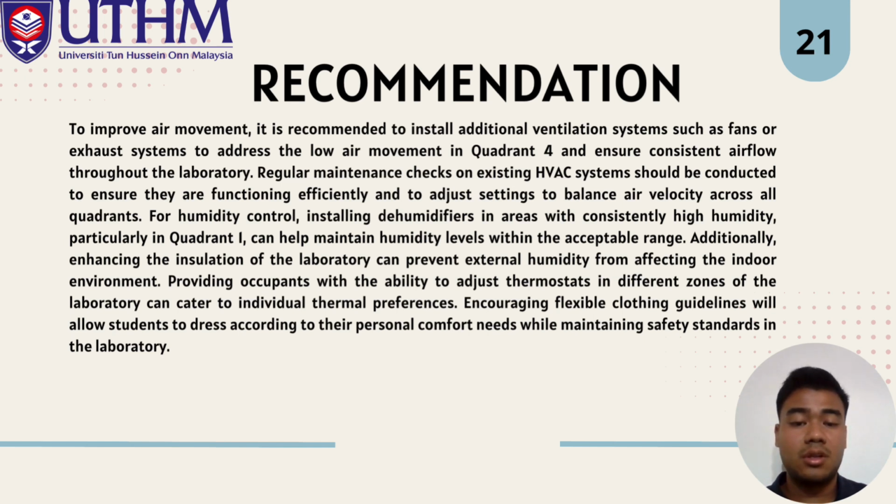For humidity control, installing dehumidifiers in areas with consistently high humidity, particularly in quadrant 1, can help maintain the humidity level within the acceptable range. Additionally, enhancing the insulation of the laboratory can prevent external humidity from affecting the indoor environment. Providing the occupants with the ability to adjust the thermostat in different zones of the laboratory can cater to individual thermal preference. And the last one is encouraging flexible clothing guidelines, which will allow the students to dress according to their personal comfort while maintaining safety standards in the laboratory.